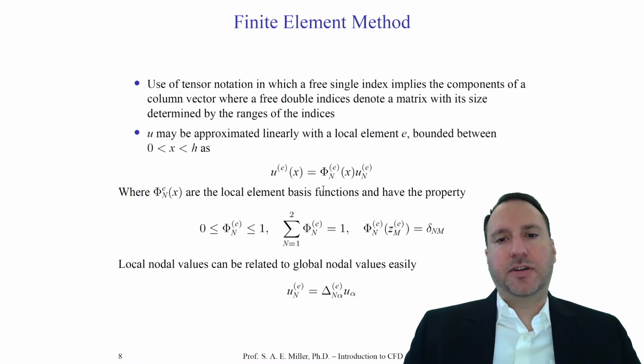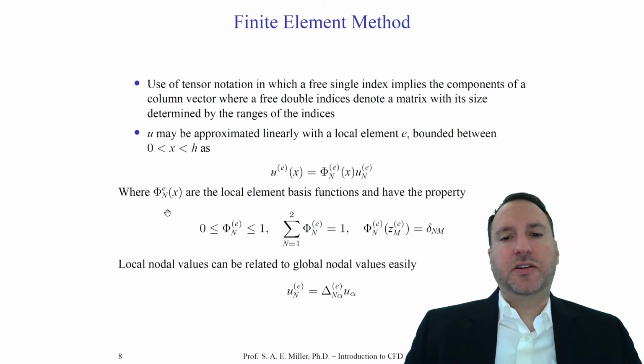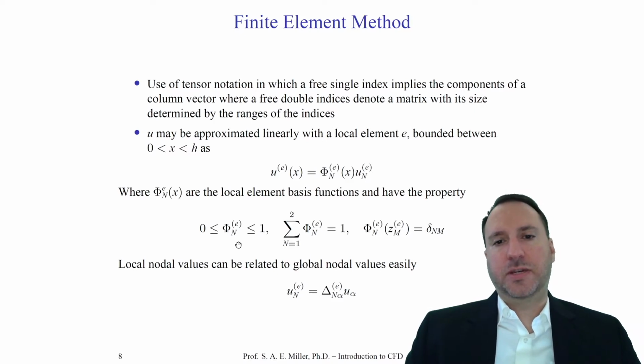This is part of what Galerkin did to decompose these domains that are very complicated for structural problems, not fluid dynamic problems. Here we define capital phi sub n sup e of x. This could also be a function of x, y, and z, mind you. Here it's one-dimensional. We'll show formulations later in this class. Here we'll say that the basis function is bounded from 0 to 1 for each element. And that means it's just a standard element. If we have an element of a different size, we can use a transformation, just like the Jacobians of structural methods, to transform it into a unit element.